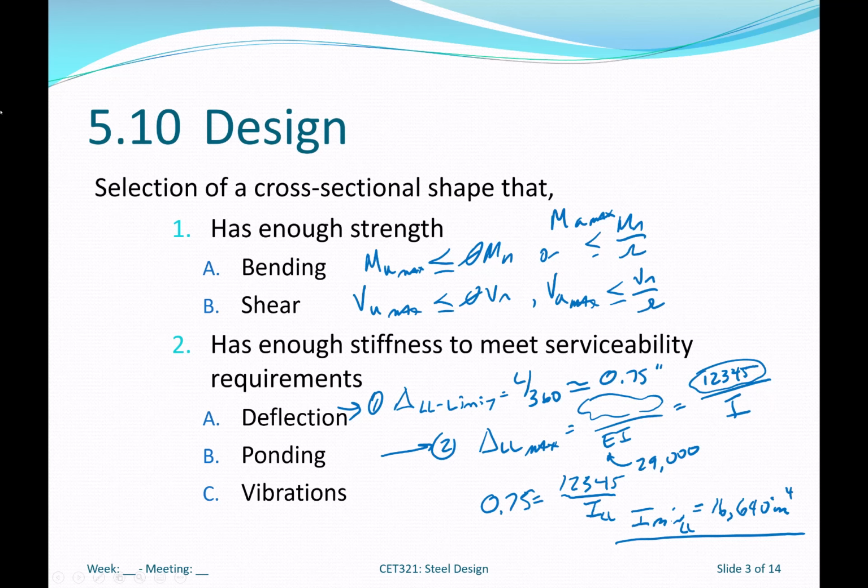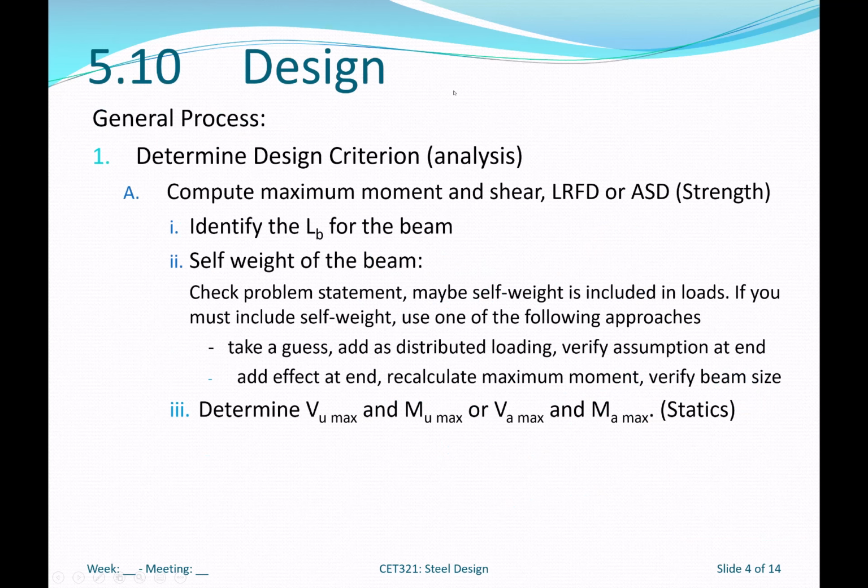It is a process, and this process is what I think works based on my experience. It will evolve as you become more familiar with it. So you have to make notes and see what works for you. First I think of design criteria, primarily my analysis. I want to gather some information, and one thing that has a major impact on the strength of beams is the unbraced length. So I want to make note of that immediately.